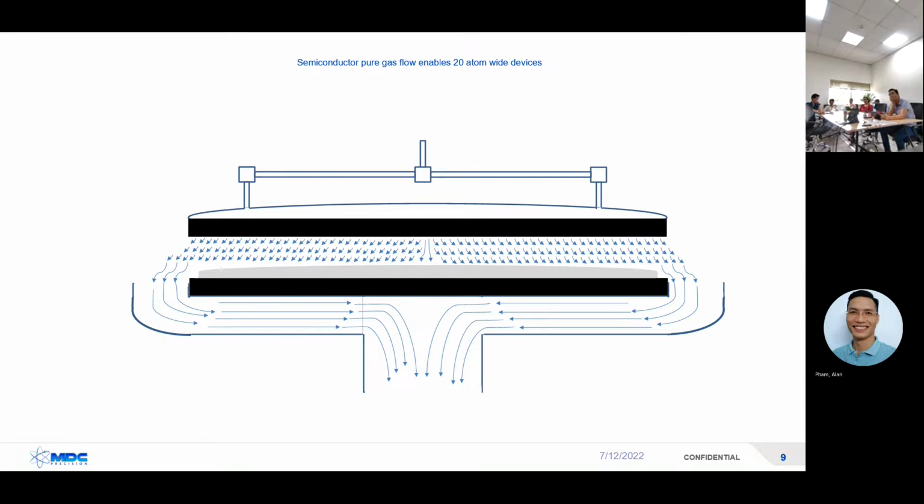So now here's the gas happily coming through an MDC line, comes down here, and the gas is flowing evenly across this whole thing. That seems simple, it's not simple. Getting even gas flow is very difficult. Once I have the gas flowing, I apply a charge up here. This is hooked out here to a generator. The generator turns on, this now has an electric charge to it. This is grounded, so you wind up with an electric circuit. In between is the gas. The gas gets excited, so now the fluorine breaks away from the carbon and is out here dancing around, and the silicon dioxide sees the fluorine dancing around, and it says, I'm going to go play with the fluorine. It grabs the fluorine, and then it gets pumped out down into the basement.